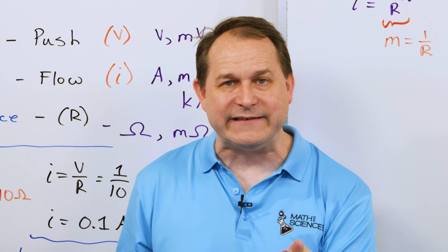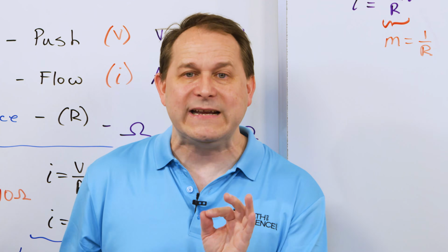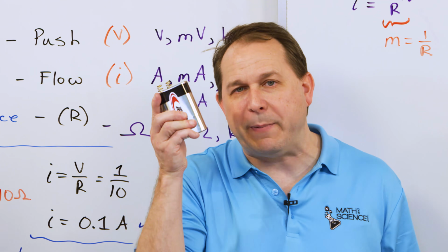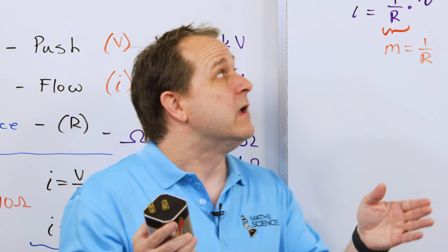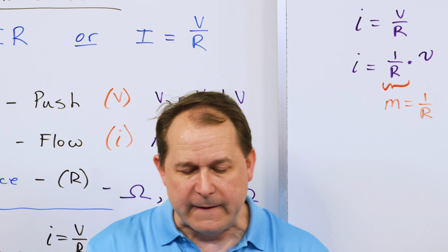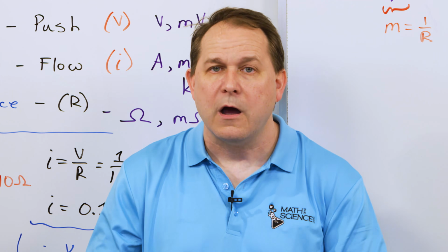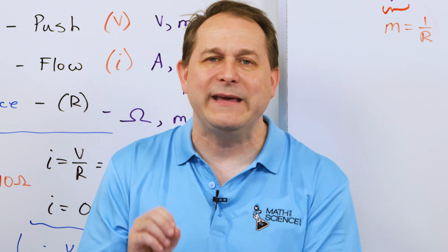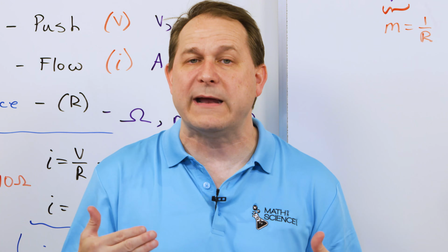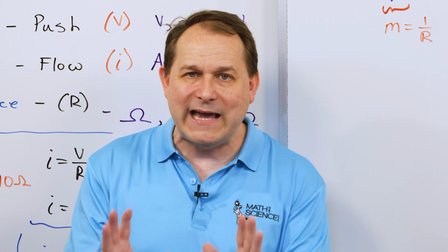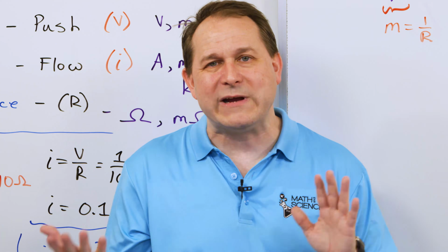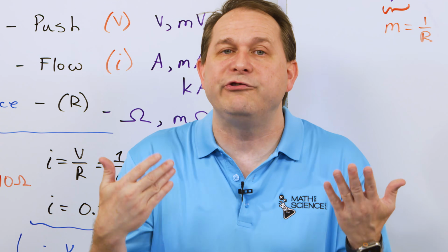But we're not going to get exactly what we got before. What we're going to find out is that the physically large battery can generally keep up and supply the correct amount of current as predicted by Ohm's law. But the small batteries are going to try, but they're not going to be able to physically source the amount of electricity that Ohm's law is calculating that you should get. So again, this is the difference between theory and reality. Ohm's law will tell you what you should get.